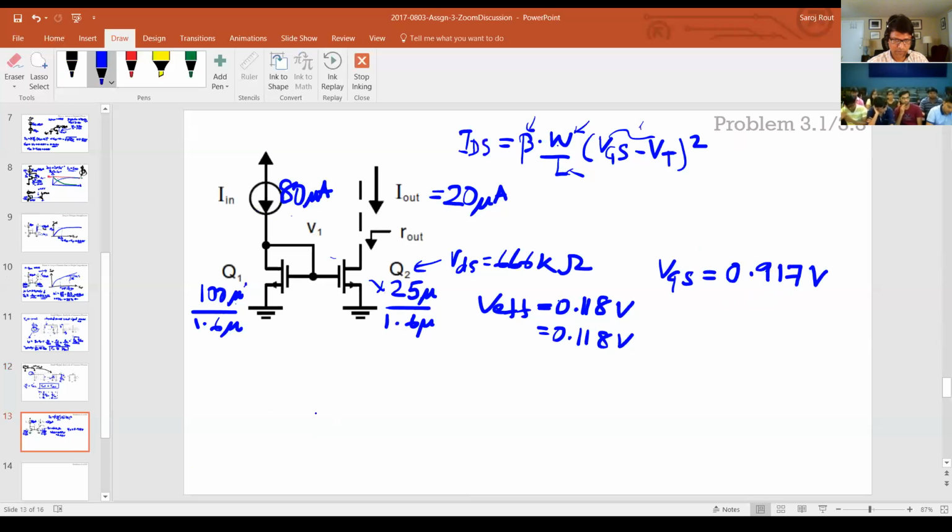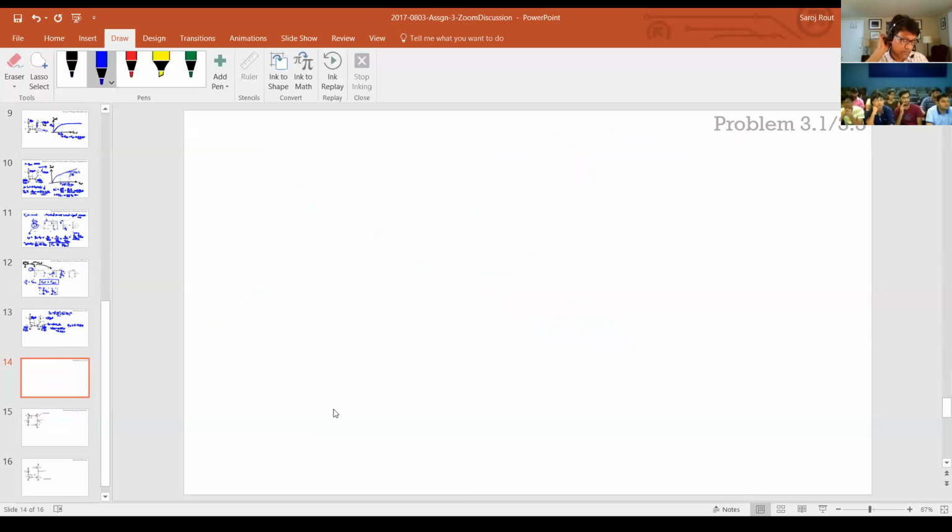And then I also followed that example where I changed the output voltage and give you the output current change. Now I'll go to the next part of the problem, which I think was given a lot of variations. And this is a very important problem because when we start doing projects, we'll see that there are a lot of variations in VT, mu, and Cox, which are called mismatch of these transistors. And that'll create a mismatch in the current. And that creates a lot of non-idealities when you're designing amplifiers or just simply current mirrors.